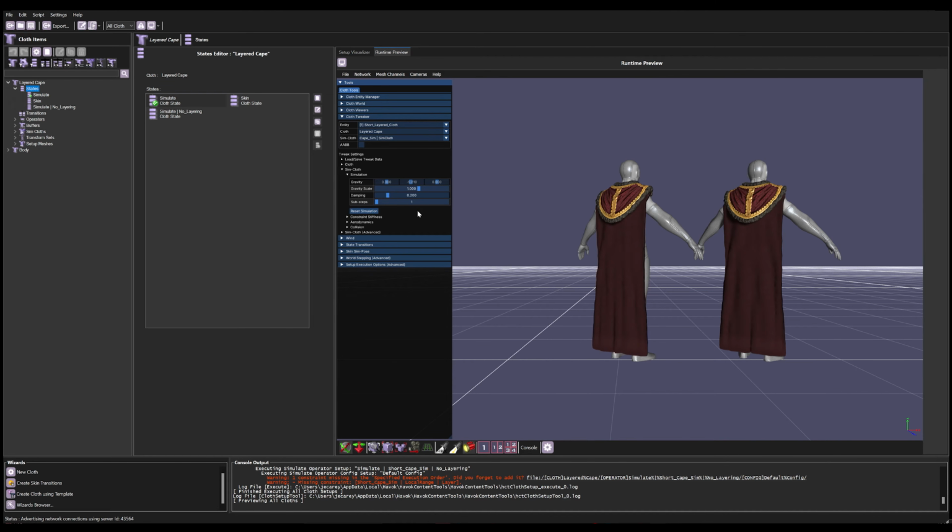The Runtime Preview tool can be used to test both new aesthetic and behavioral cloth values. So let's look at tweaking the cloth aerodynamics. Expand Wind Settings, change Wind Type to Aerodynamic. This means the wind type will take into account all the settings that we are going to set in Wind Properties. Set Wind Active to On.